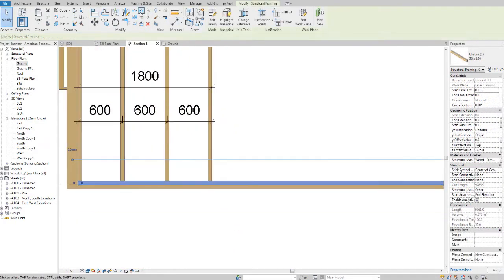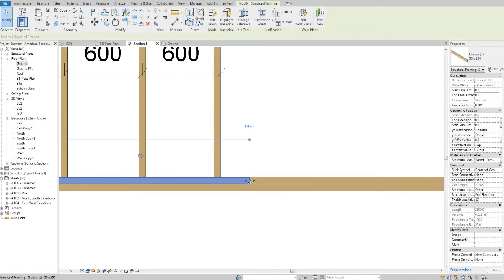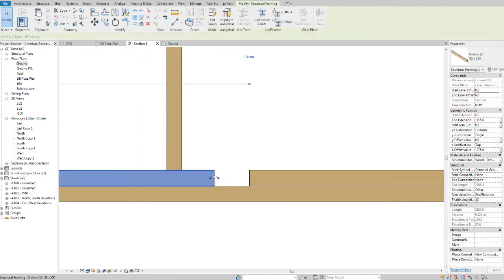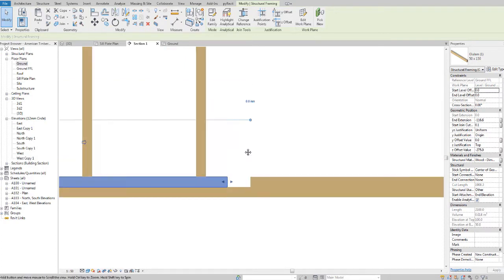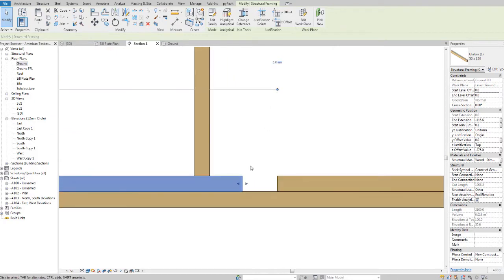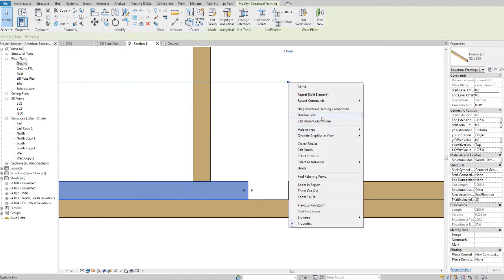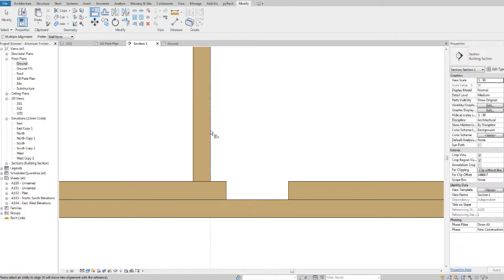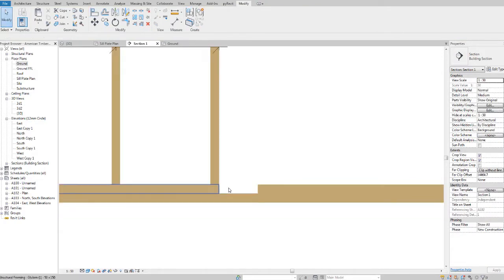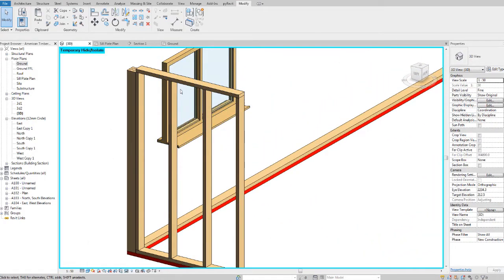And this bottom rail, I'm going to cut it anywhere, doesn't matter. Pull this back, and I'm going to right click this as well and disallow join. You can also click, there's a symbol somewhere to disallow join. If I see it, I'll let you know. Disallow join, and use the align to get it perfect. There we have our first timber frame.